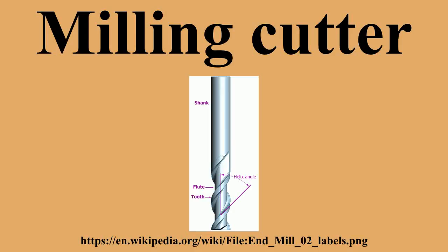HSS tools are perfectly adequate for many applications. The progression from regular HSS to cobalt HSS to carbide could be viewed as very good, even better, and best. Using high-speed spindles may preclude use of HSS entirely.